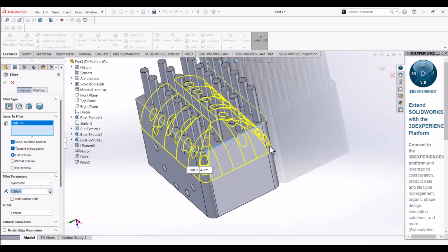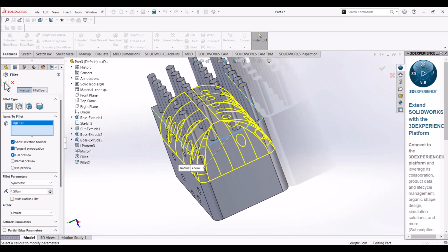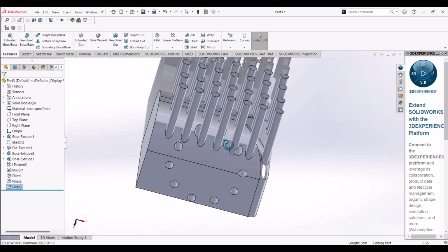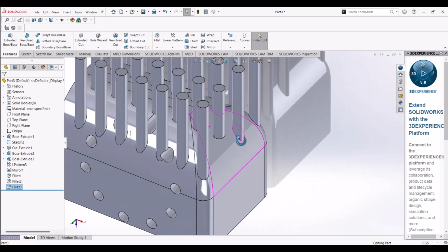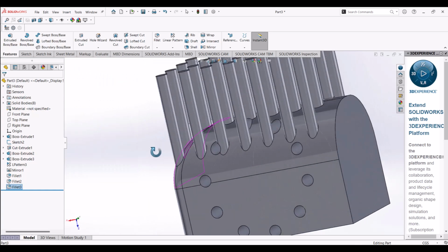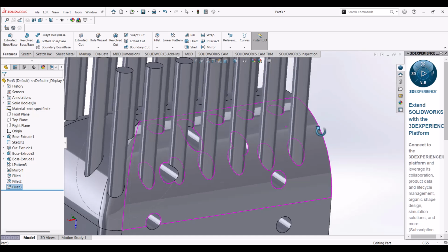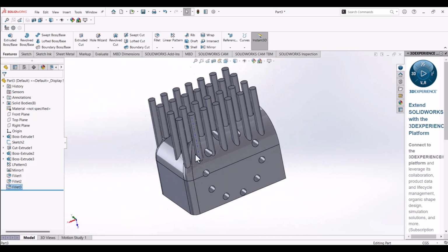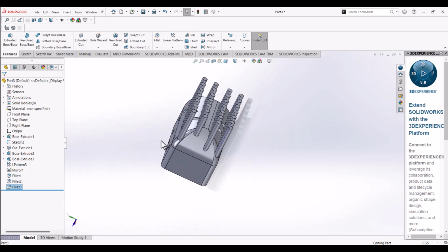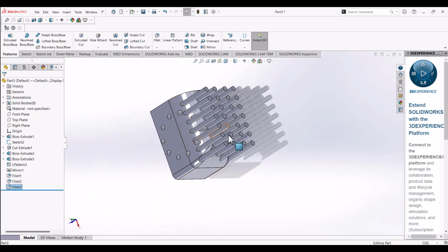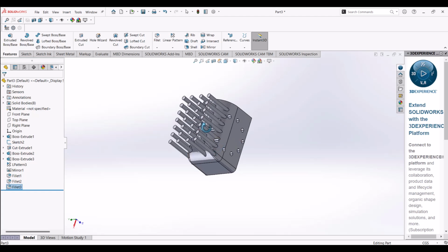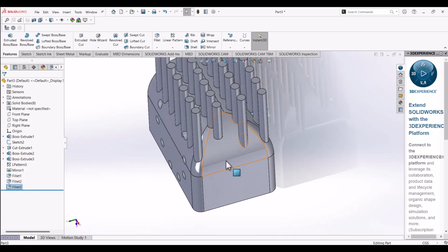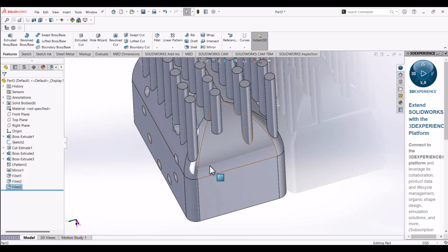So let's look at something like this. Let me accept it and let's see what happens. You see now the whole thing has changed. Look at how it has made it. At first the thing was rectangular. Why it didn't affect this is that it is a separate body, so it's only applying the fillet to the rectangle I created.